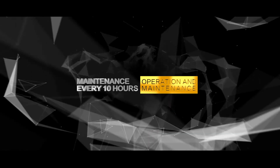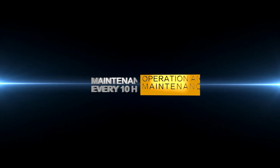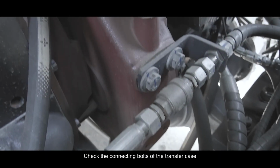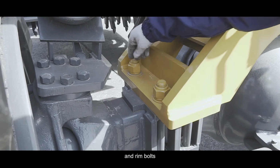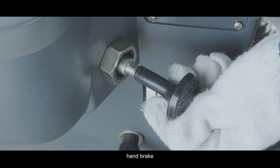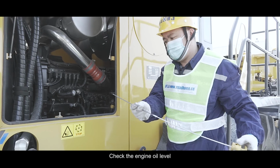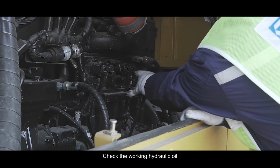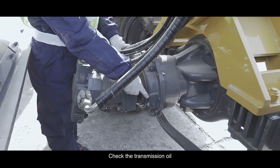Regular maintenance. Maintenance every 10 hours. Check the connecting bolts of the transfer case, engine and rim bolts. Check the throttle control, handbrake, foot brake, and gear shift control system. Check the engine oil level. Check the working hydraulic oil. Check the transmission oil.